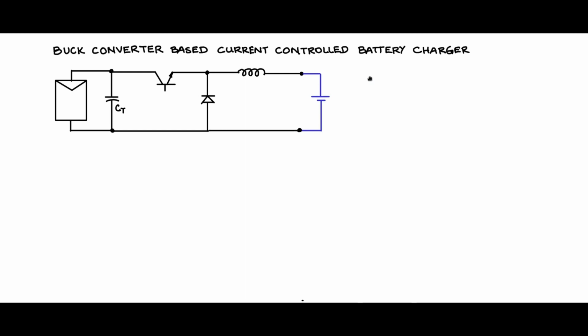And across the battery you may have the load or not, like this. Because the battery here fixes the potential across the output terminals of the DC-DC converter, the current through R0 is decoupled from the rest of the circuit operation.